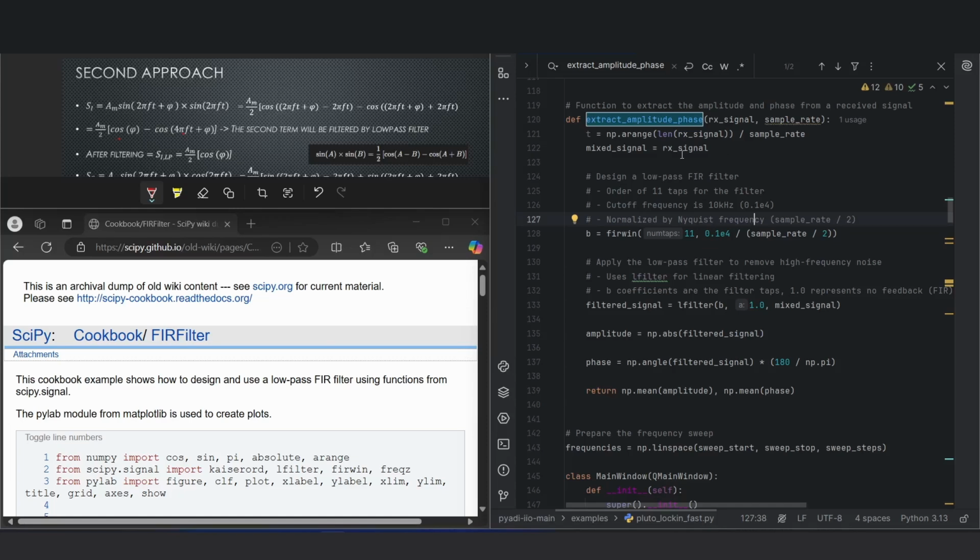If you watched the previous video where I discussed this in detail, we know that we have a sine wave and we want to find its amplitude and phase. When we multiply by a cosine, we find a term Am over 2 cosine phi, or when we multiply by sine, we have a sine phi here.